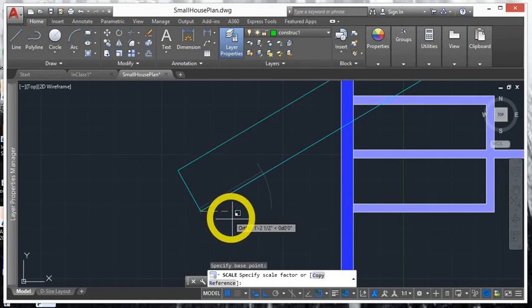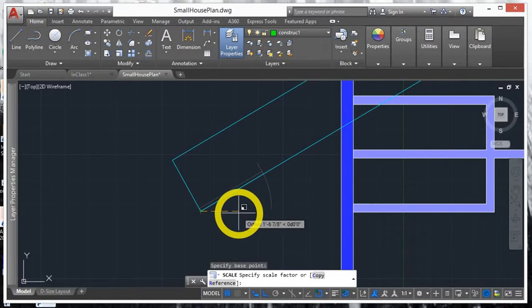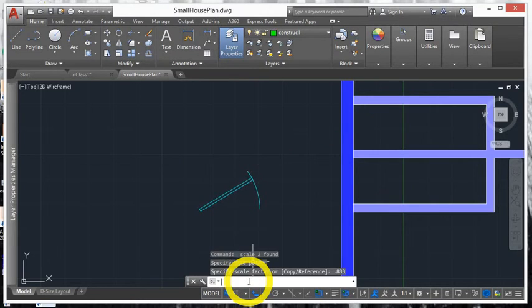And you'll notice as I drag the cursor back and forth, the object gets wildly and inappropriately larger. But we're going to do a scale factor, and I've already calculated the scale factor for us. We have a 36-inch door. We want it to become a 30-inch door. So 30 divided by 36 is 0.833. So here in the command prompt area for our scale factor, we're typing 0.833. We're pressing enter. And that has scaled the door down to be suitable for an interior door now.